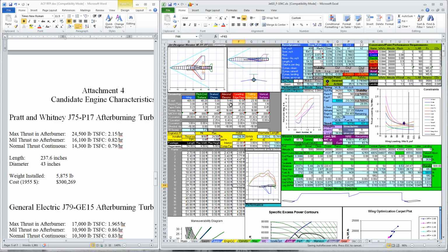So the way we do that is we take our ailerons, and for each, we're doing an autosave. For each entry for the aileron, we have to make it equal to the entry for the trailing edge flaps, and then it'll become flaperons just like the F-16 uses. So here's an area, here's an aspect ratio, here's a taper ratio, which is the same, here's a sweep, which is also the same, here's an airfoil section, which we can't use the copy function there because of the formatting of that particular cell.